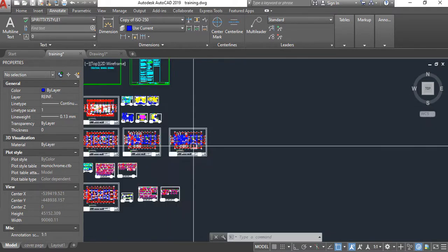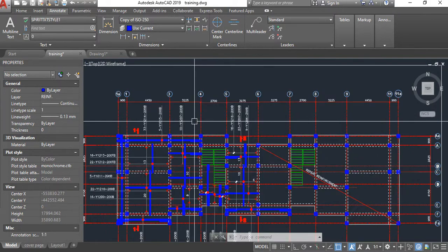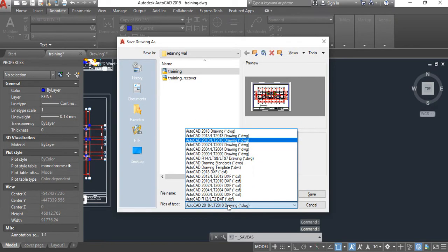Maybe you delete every other drawing and leave just one on your AutoCAD, then go to Save As. If there is this feature here, converting AutoCAD to DXF file, then you can import directly to ProtaStructure.